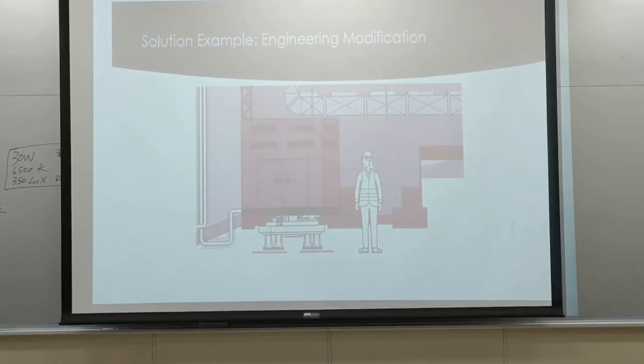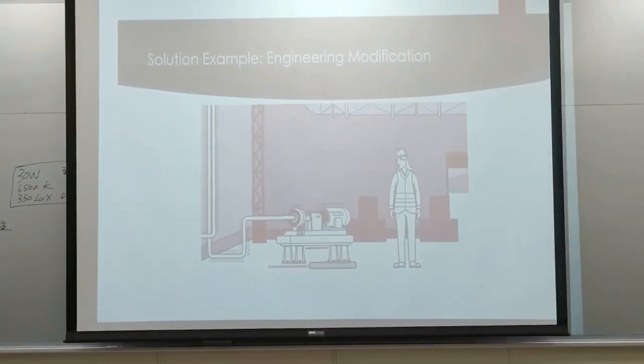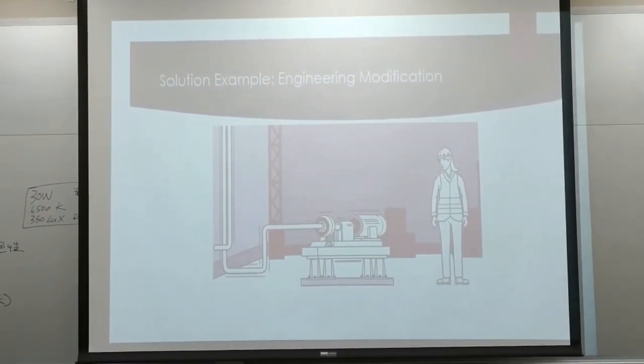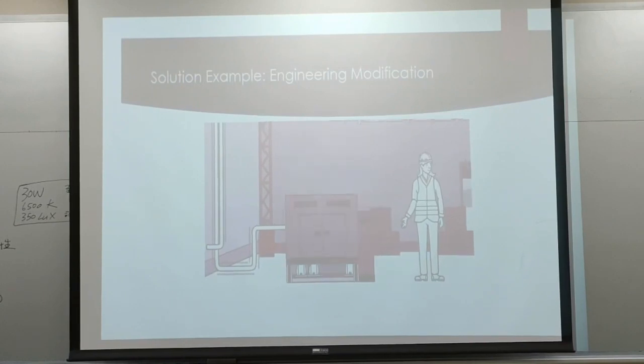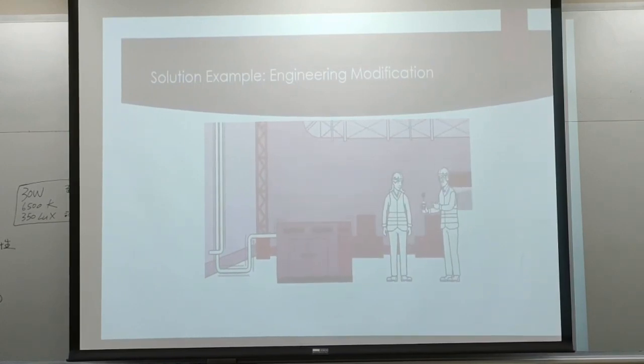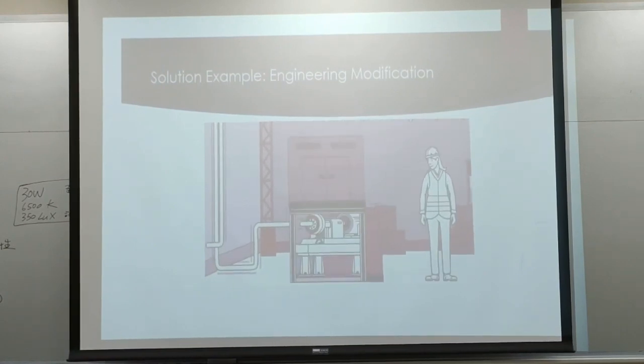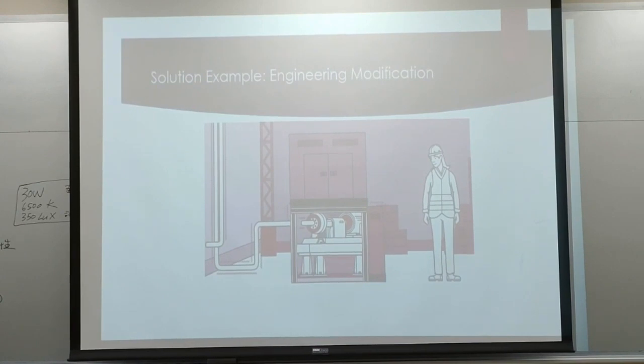To reduce vibration moving to other surfaces, fix your machine onto a smaller surface and reduce the noise the rattling creates by making its housing more compact. Also, line the surface the machine is mounted on with sound-absorbent materials. An acoustic engineer can help you identify which sound-absorbent material is right for your machine. Or choose a more flexible material. Instead of mounting your machine onto a hard surface, use wire mesh or perforated metal.